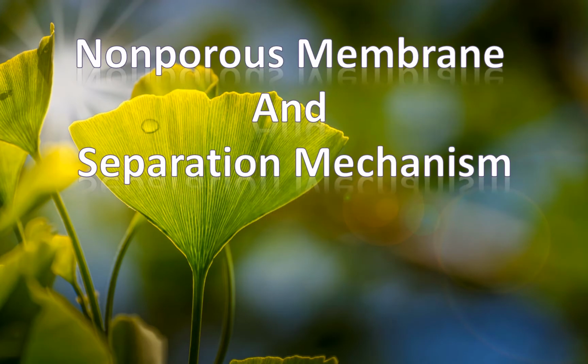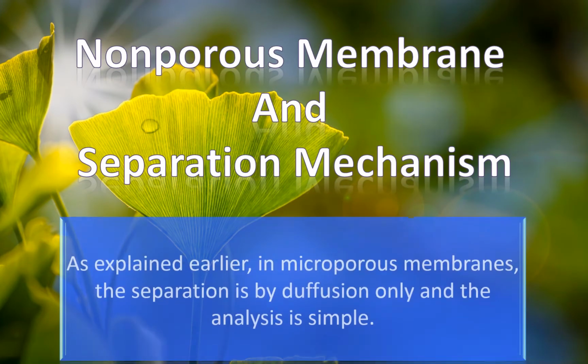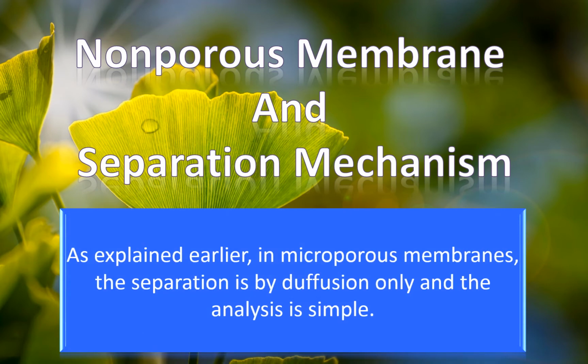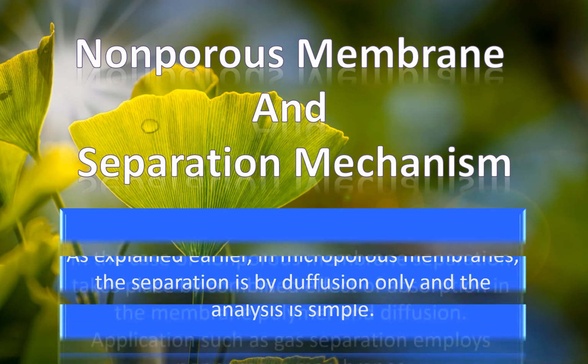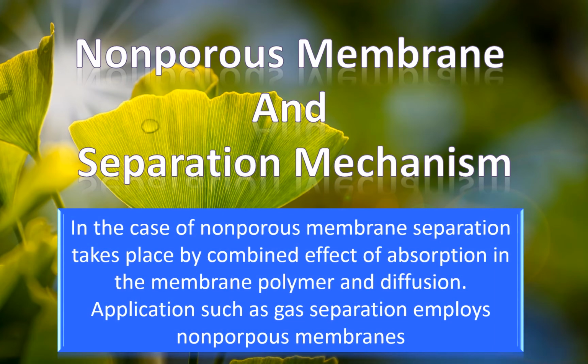Non-porous membrane and separation mechanism. As explained earlier, in microporous membranes, the separation is by the diffusion only, and the analysis is simple. In the case of non-porous or dense membrane, separation takes place by combined effect of absorption in the polymer and diffusion.